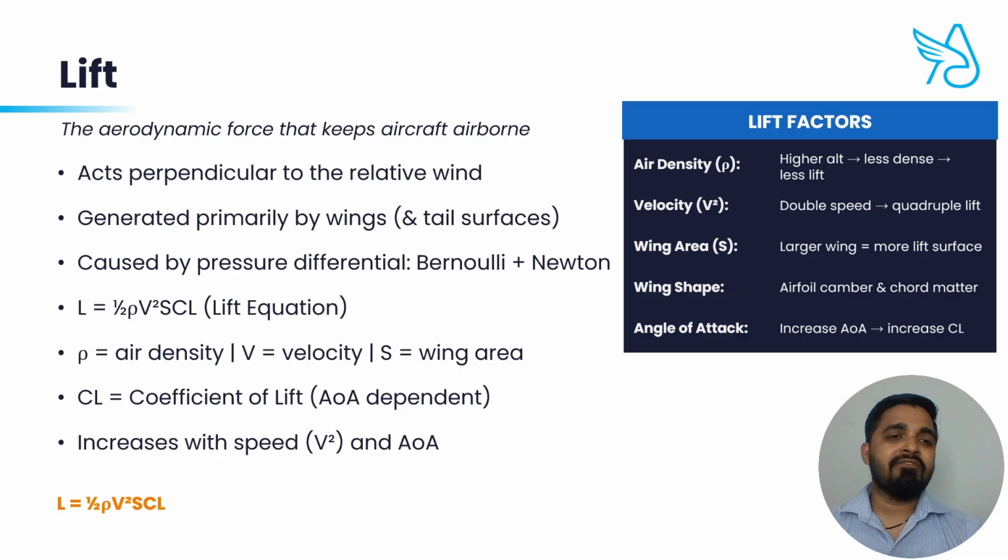Now the second aerodynamic force, the lift. This is the force that keeps the aircraft in the air. Now on the screen here is the equation of lift. Let me break it down in short. Here L means lift, which refers to the force that we want to generate. Rho refers to the air density, which means how thick the air is.